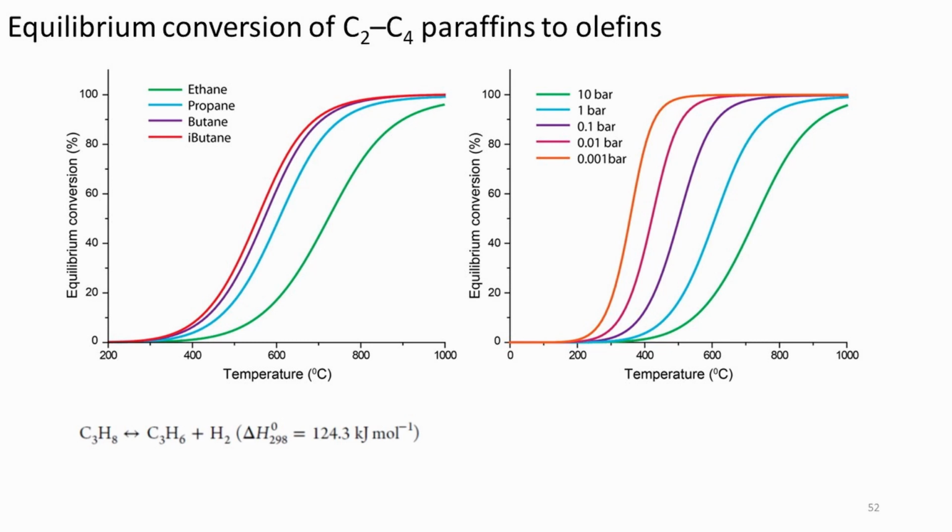Indeed, temperatures of 550–750 degrees are typically required in dehydrogenation of C2–C4 paraffins to obtain alkane conversion of more than 50% at 1 bar. Moreover, given that the enthalpy required to dehydrogenate alkanes decreases as the chain becomes longer, a large amount of energy is required to dehydrogenate light paraffins on a molar basis.